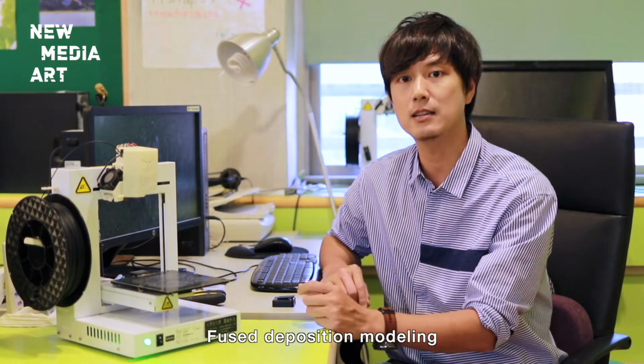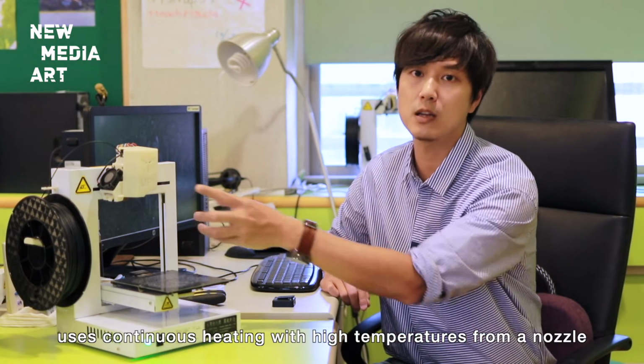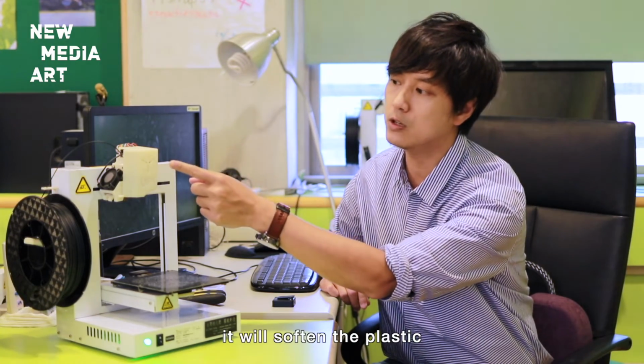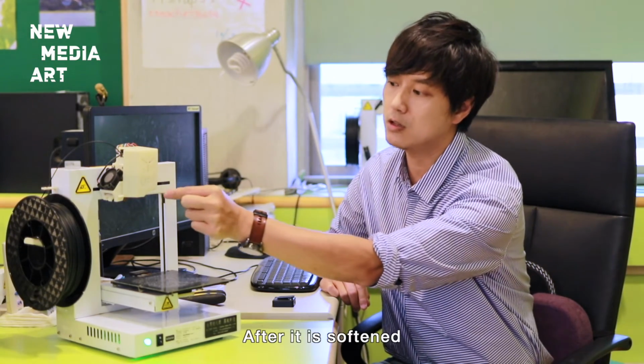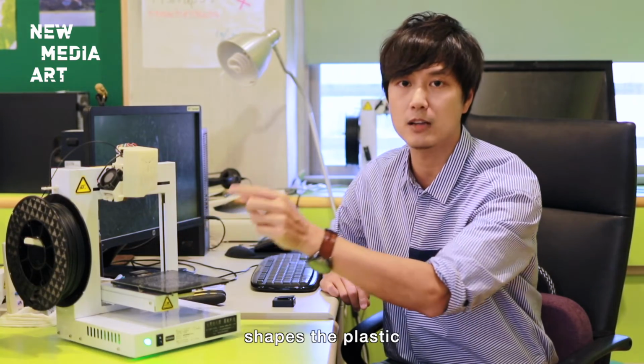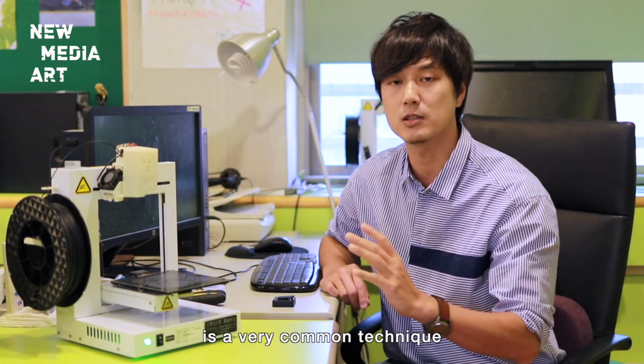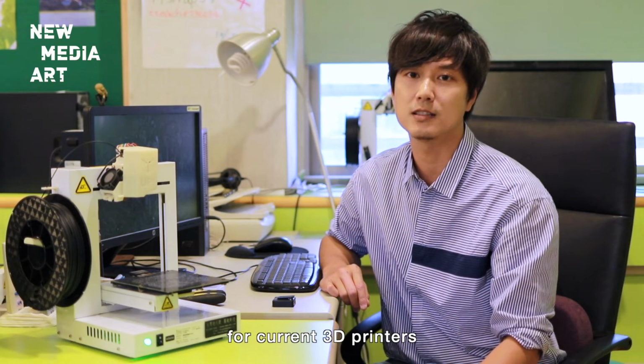Fused deposition modeling uses continuous heating with high temperatures from a nozzle. When heated to a certain degree, it will soften the plastic. After it is softened, the nozzle then shapes the plastic. This fused deposition modeling technology is a very common technique for current 3D printers.